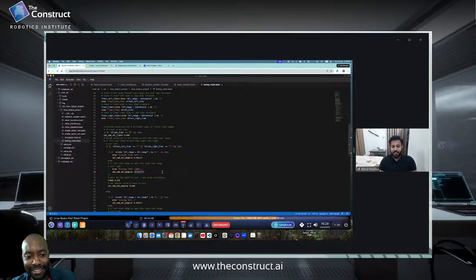I did the testing, and it sometimes collided, but I optimized and increased the minimum time. Previously I put 0.3, then I increased it to 0.4, then 0.5, and after that it didn't collide. So I did the trial and error thing.